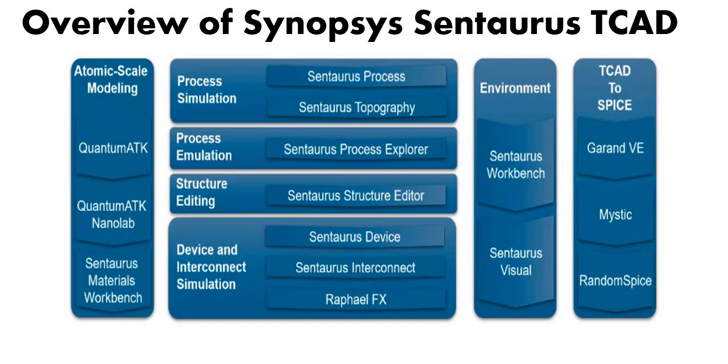Next is the device simulator, in which the device simulation is done with the help of the Sdevice simulator, which studies the electrical characteristics of silicon based and compound semiconductor devices, such as response to external electrical, thermal and optical boundary conditions.